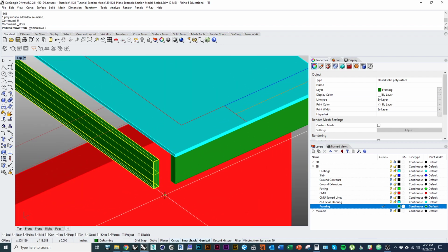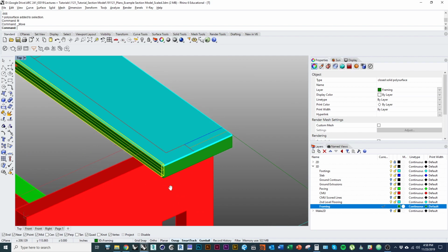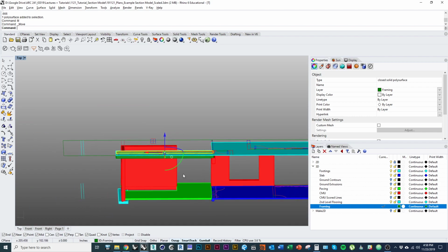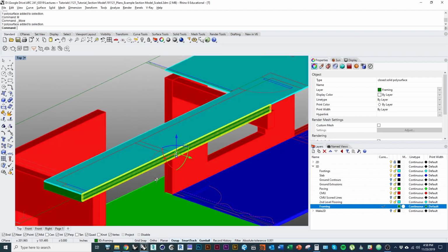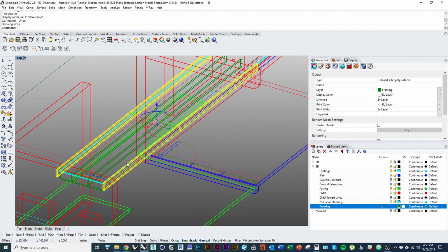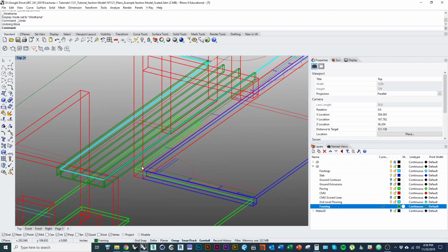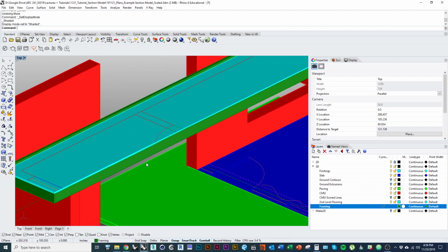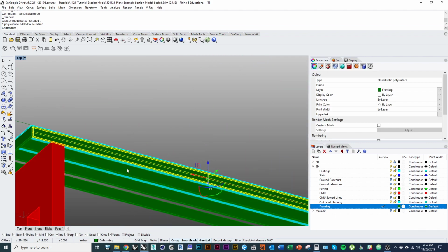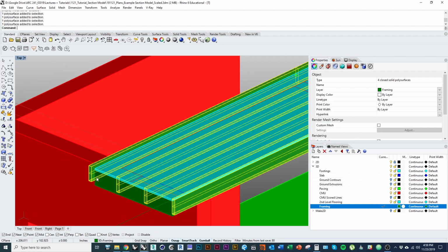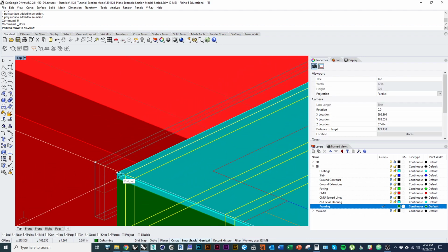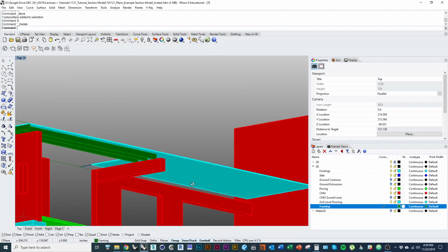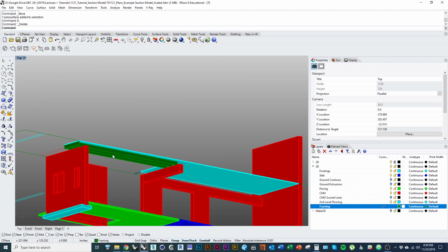Alright, and so as I was mentioning before, we actually want to make sure that we have a kind of exterior frame that goes all the way around at the edge, at the thickness. So there we go. And actually what I might do instead, because this kind of spacing is arbitrary, right? The fact that we drew the first edge right here, I should have started from that outside edge, that makes more sense. So what I'm going to do instead is just move all these floor joists over so that it meets the outside edge there, and then I'll just delete this one. So we kind of get a sense of the fact that we're cutting through the geometry right there. We're just seeing that floor framing below.